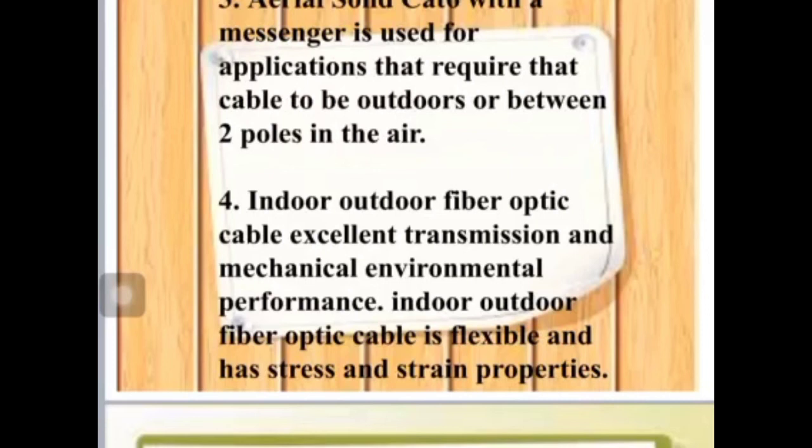These types of cable eliminate the need for a transition splice to an indoor rated cable when routing outdoor cables into a building. When routing cables within a building, you will also need to factor in fire prevention requirements.